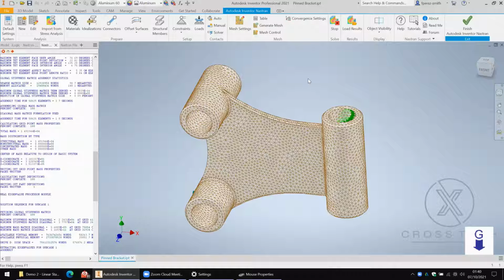Okay. So in the case of modal analysis, we're interested in two things. What we have here are the eigenvectors. So here we go, we've got mode 1. Its natural frequency occurs at around 293 hertz. Mode 2 occurs at 1048 hertz. Mode 3 at 2200 hertz.